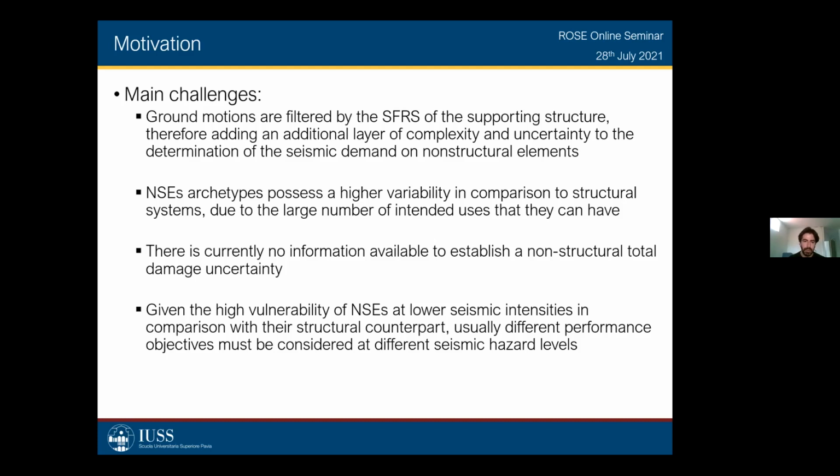And finally, non-structural elements have the characteristic that they are much more vulnerable at lower seismic intensities than their structural counterparts, which means that when you assess performance of non-structural elements, it's very important to actually assess the performance at different limit states.